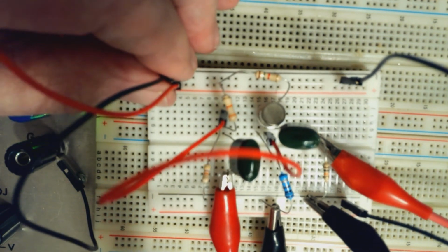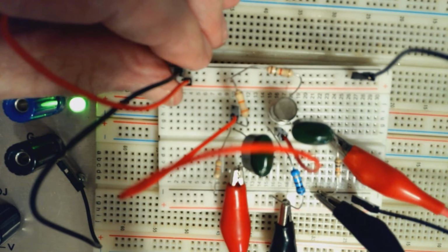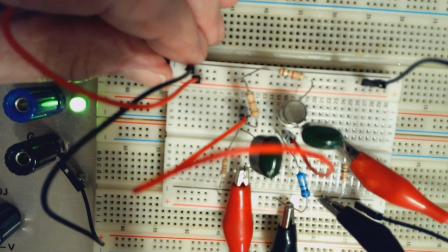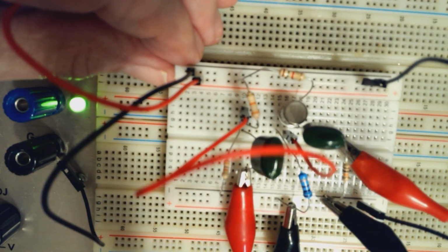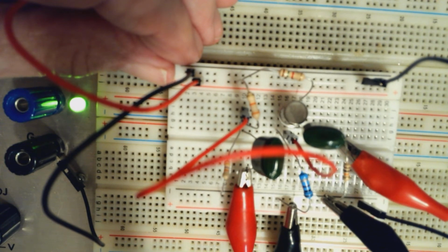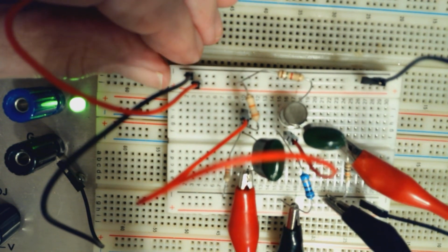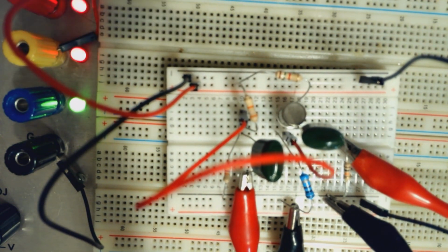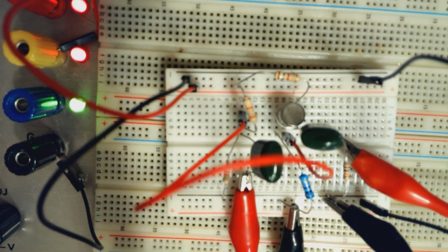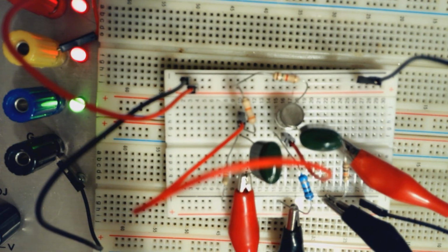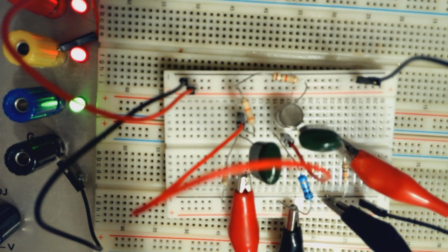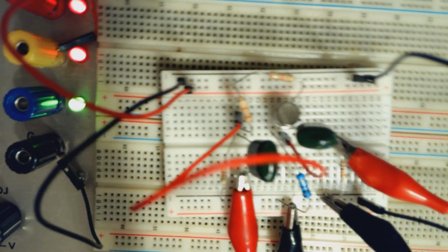Years ago, when we had discrete circuits, people had to design these things, and of course today we have integrated circuits where we can program what the gain is. So right now I've got a 1 kilohertz signal at 200 millivolts peak to peak going into this amplifier. Let's take a look at the output on the oscilloscope.